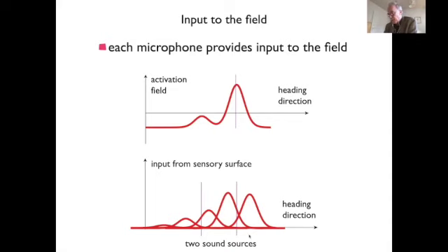So we're taking the raw response, and so you see here, for instance, this sound source was louder than that sound source. That's why these two microphones that are pointing this direction respond more than these microphones. And so what we do as a sensor interface is simply take the intensity to rate code transformation. The physical device, the microphone and its electronics, is a model of a sensor that transforms a physical intensity into a rate code.